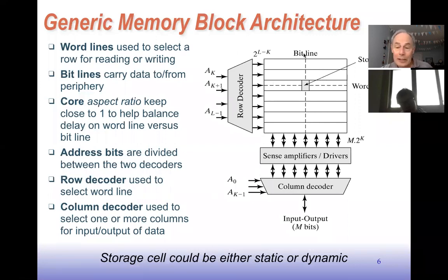But as we'll see, these wires connect to the bit cells, and every place where it makes connection to the bit cells, there's added capacitance there. There's typically a fair amount of bit cells in this direction and in this direction. Therefore, that's a highly capacitive line. So to optimize the sum of the delay on the word line and the bit line, we tend to balance those out and make this relatively square.